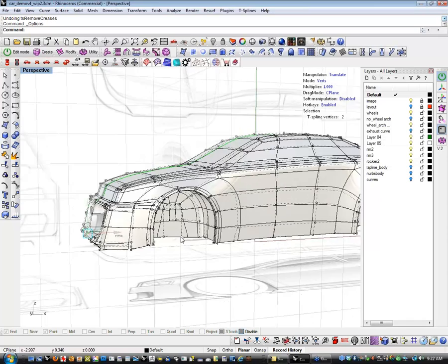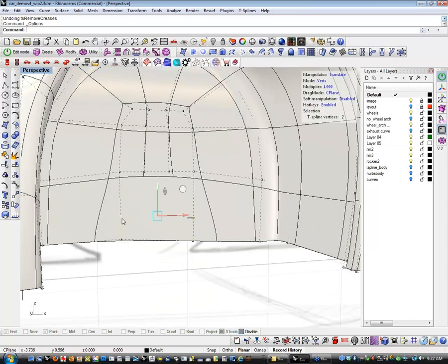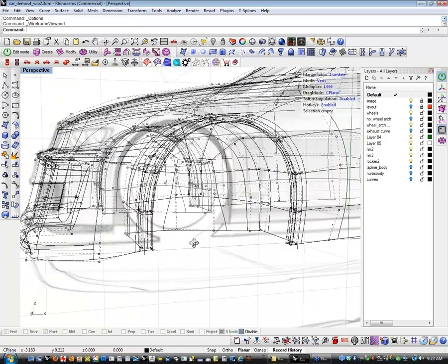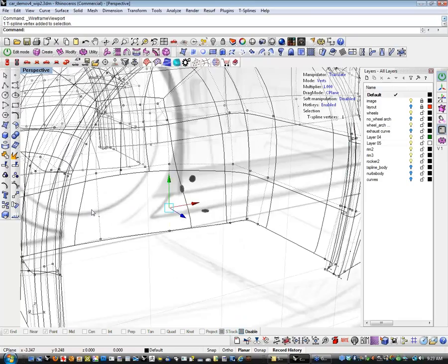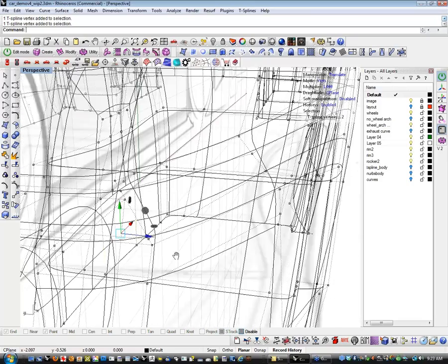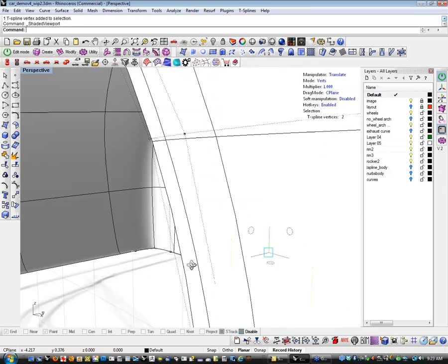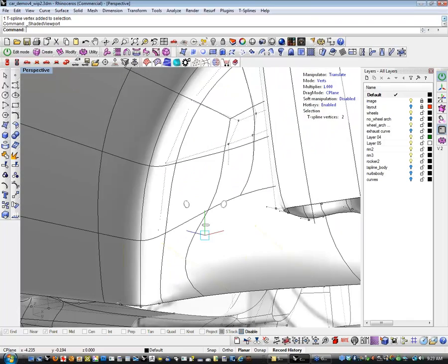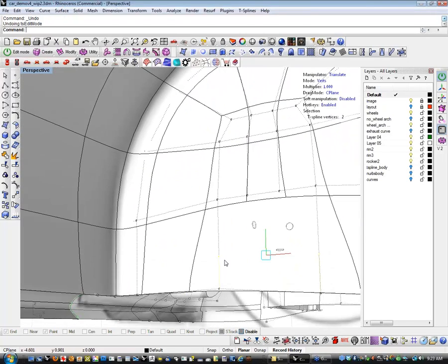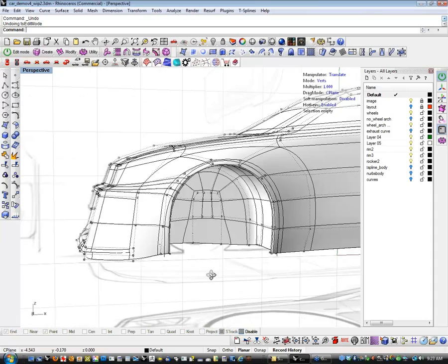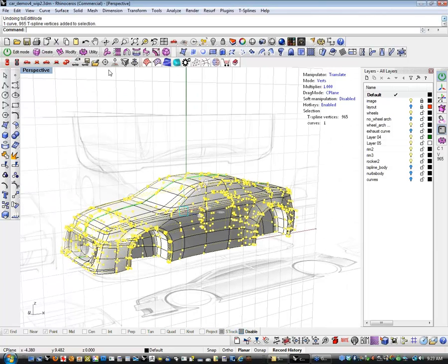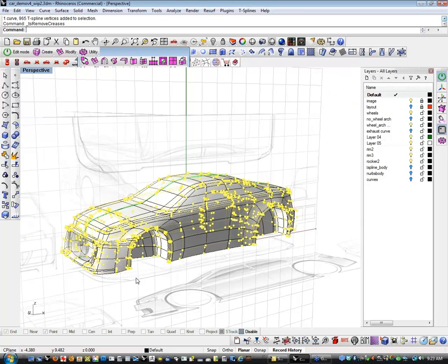In this case, I don't necessarily want anything to be happening there. You'll notice that they're all around the model here, these extra little dots. It might be easier to see if I unshade them. As I pull these, I can affect what happens to the edge of this surface. In this particular case, I don't want anything going on there, so I'm going to select all my points and right-click on the crease tool to remove creases.